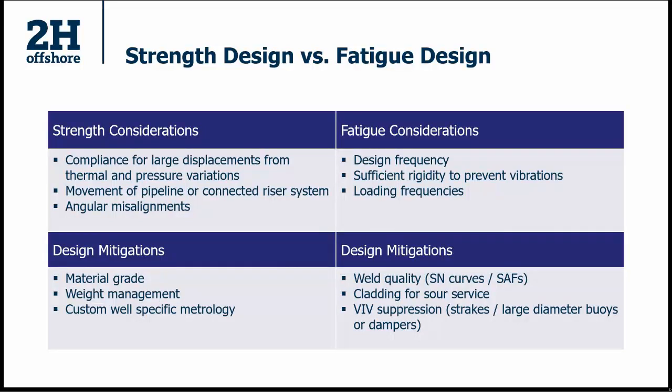You can also optimize the design by not over designing the jumper so that they are not excessively heavy, by managing the weight either by optimizing the wall thickness or putting buoyancy modules on them. You can control the weight and hence your end loads. And finally, an important tool designers have at their disposal is doing a very custom specific design. And by that, what I mean is when you're installing your subsea systems like your PLETs or your wellhead